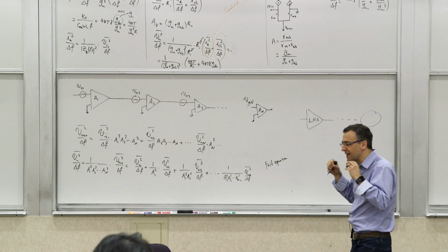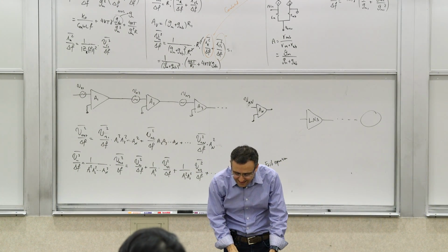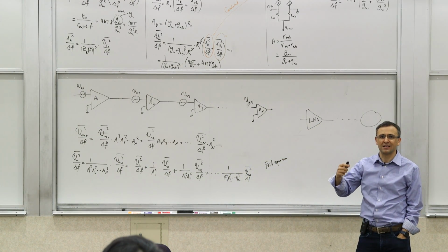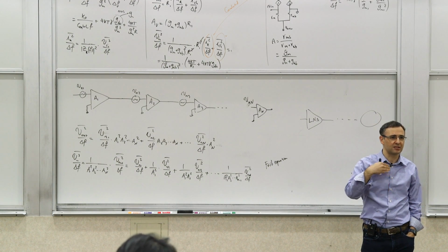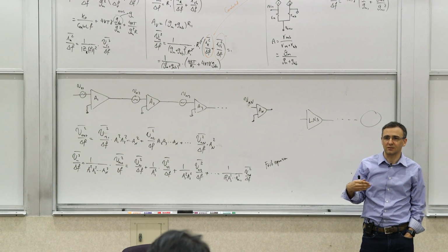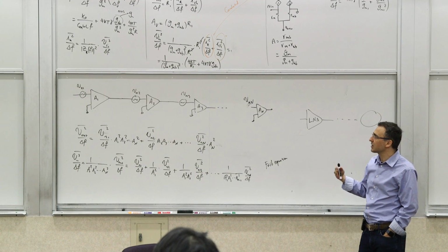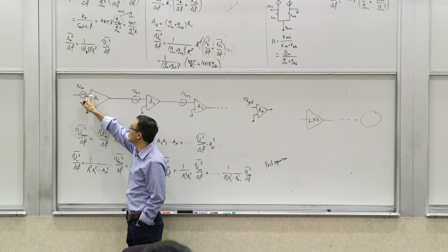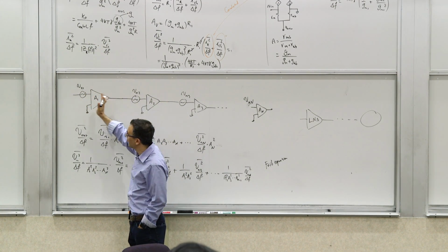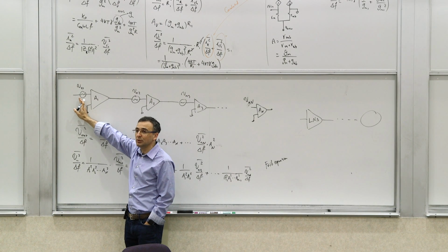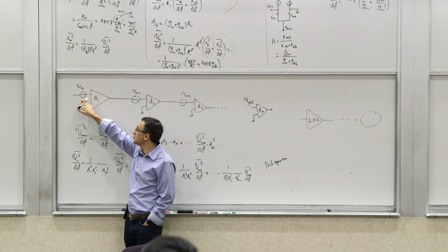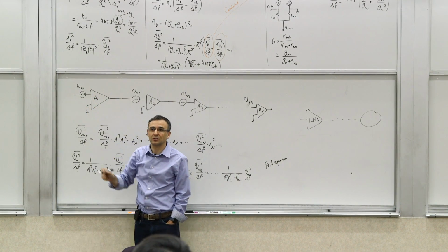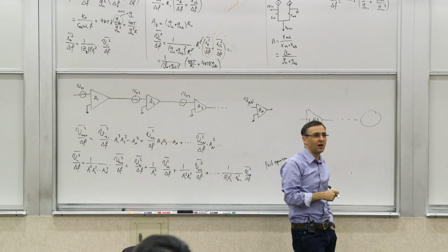This gives you a very basic foundation for dealing with noise and understanding how it progresses and is processed in a circuit as you deal with various kinds of transistors. We saw that there are various kinds of sources, and we can abstract them away into input-referred noise sources. In general, there will be a current source and a voltage source, and all of that can be reflected again to the input as a pair of noise sources, and we'll see that the input amplifiers play the most significant role in the noise performance of a system.